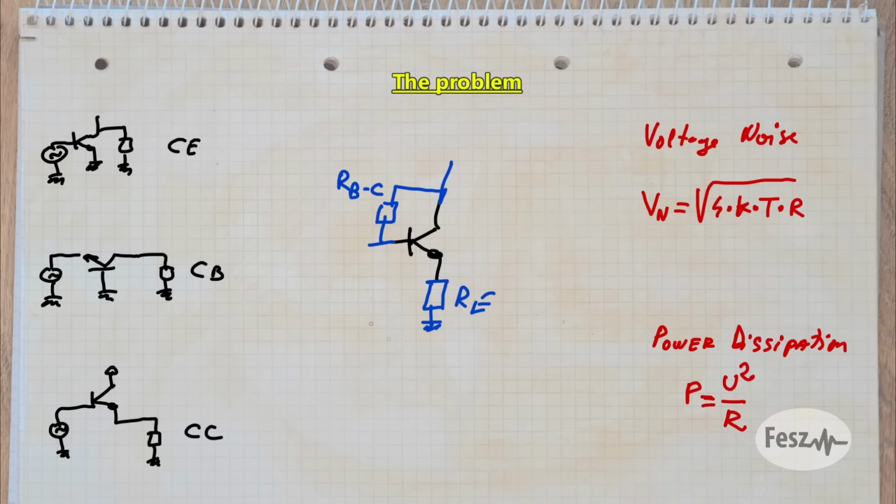So the issue we're talking about today is how do you create a frequency-independent negative feedback system which does not add noise and does not waste power? Well, you should use reactive elements. At least with the ideal components, there is no resistance in there. But this isn't all that simple either. Reactive elements have a tendency to have frequency-dependent properties.